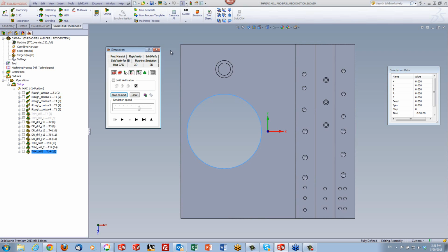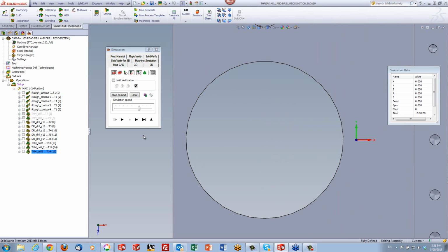When it goes in, what actually happens? It goes in directly in the middle. Then it goes to the side and then works its way around the part itself. Everything is really nice. The problem with this is that since this is a very large hole, 150 millimeters, when it goes to the center over here, it takes a while. In other words, it goes according to G1 to this area over here and then goes on. In other words, there's a lot of wasted time over here.